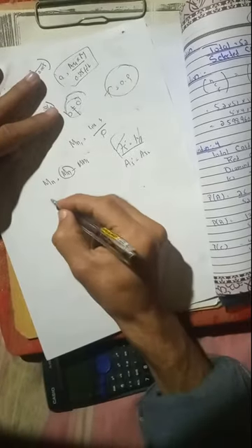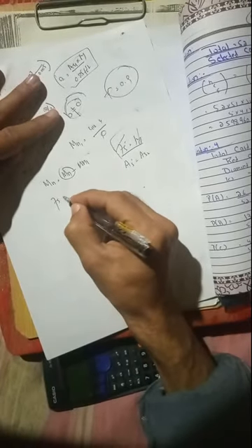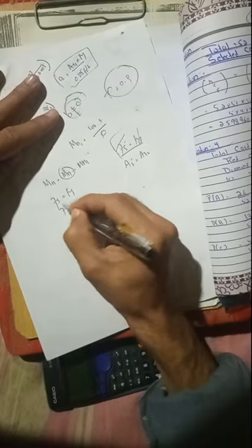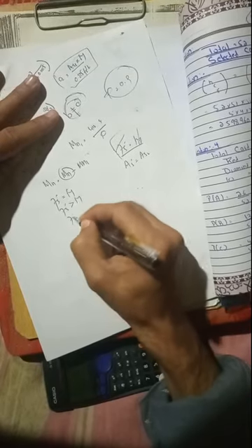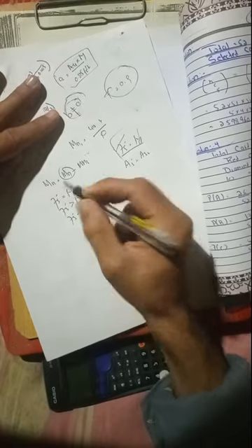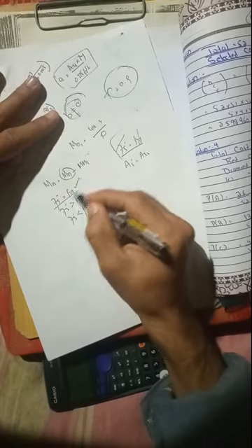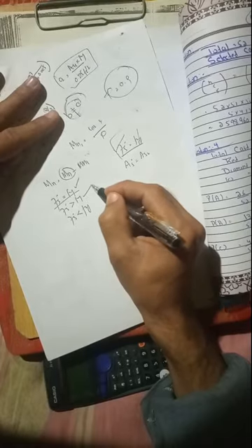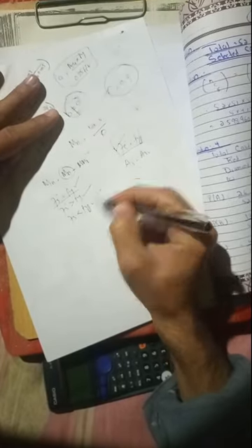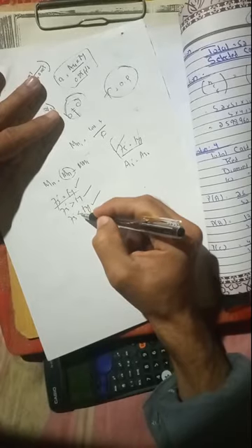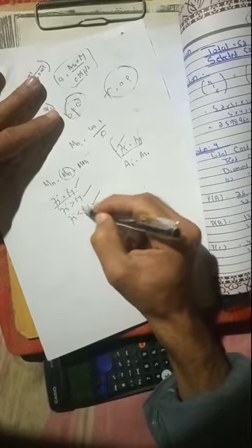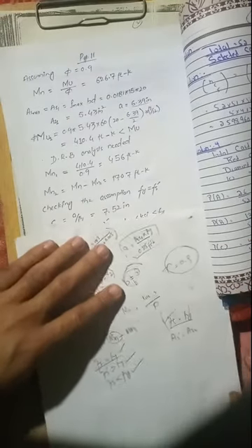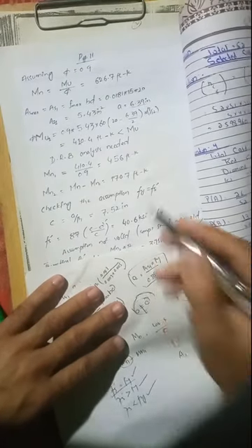So now this is the stage where we need attention, right? Because I already mentioned that you have to check your fs prime value, whether it is equal to fy, whether fs prime is greater than fy, whether fs prime is less than fy. If it is satisfied, this means balanced failure. We are okay. If it is greater than, it is also okay. This is ductile behavior. But at this stage, this means your compression steel is still not yielding, right? So how do we ensure a ductile failure? This is another type of problem, right? So the assumption is not valid. This assumption is wrong, and we have to calculate the As2.